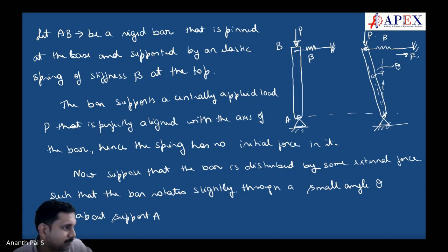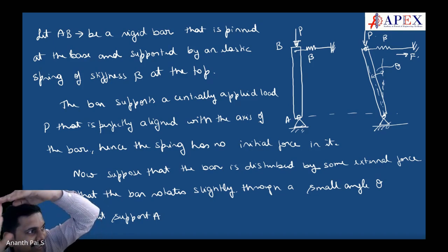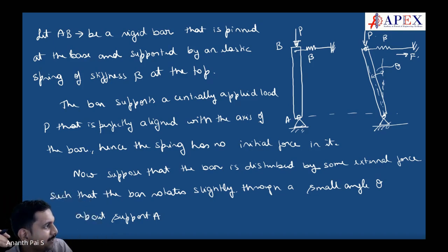Here at the spring, we are illustrating the mechanism. Now, in such mechanisms, when it is bending, what is happening? The bending stiffness shows what the stiffness of the spring is. Instead of a spring, when it is buckling like this, it is the bending stiffness which is trying to hold it back. You understand? This is idealized. Got the point? Buckling is actually due to bending, right?